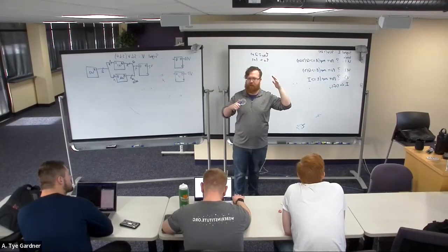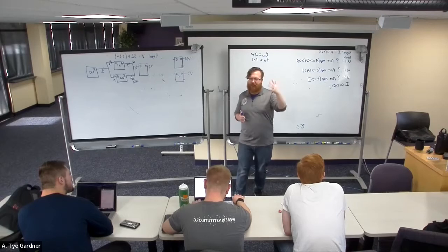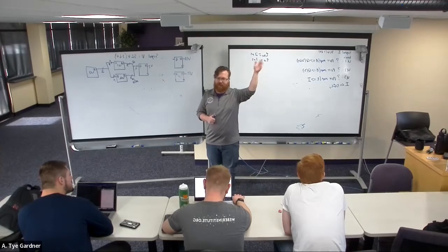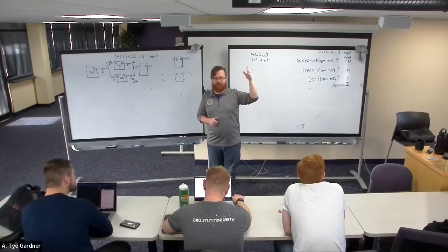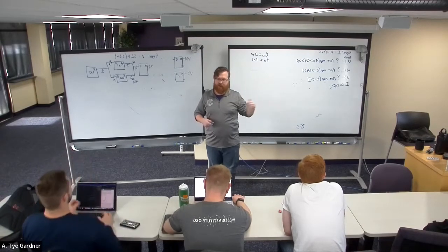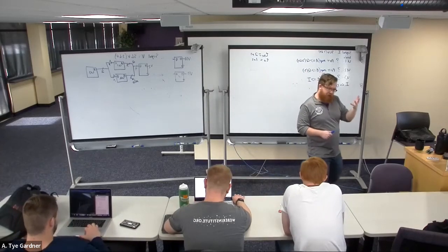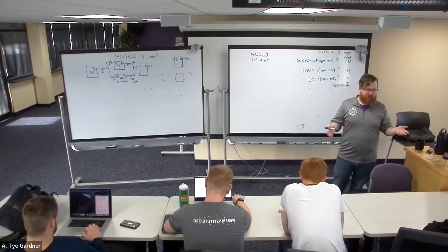Do we remember why it's a 3-bit select? It gives you enough options. Yes, because if there are 5 inputs, 2 to the 3 is 8, which is more than 5, but 2 to the 2 is 4, which is less than 5. So I need 3 bits. That's the minimum number of bits that my select signal can handle. So I have a 5 input mux that we're going to write using just a when else statement, right?